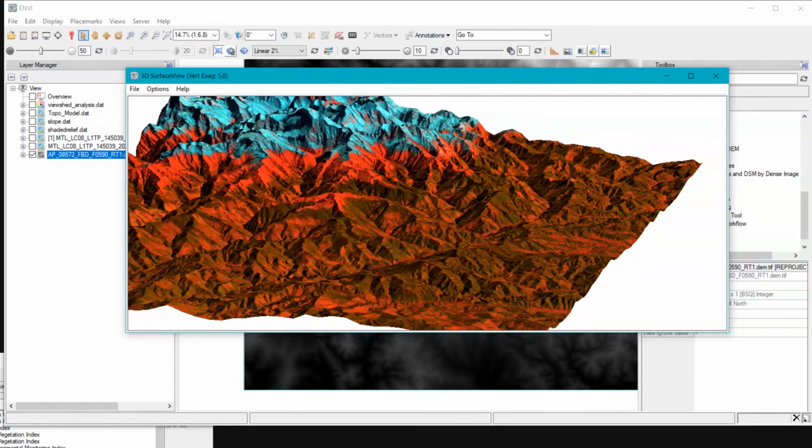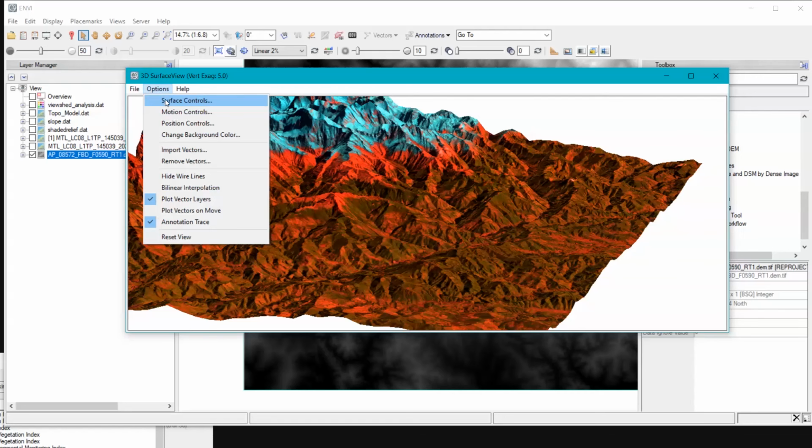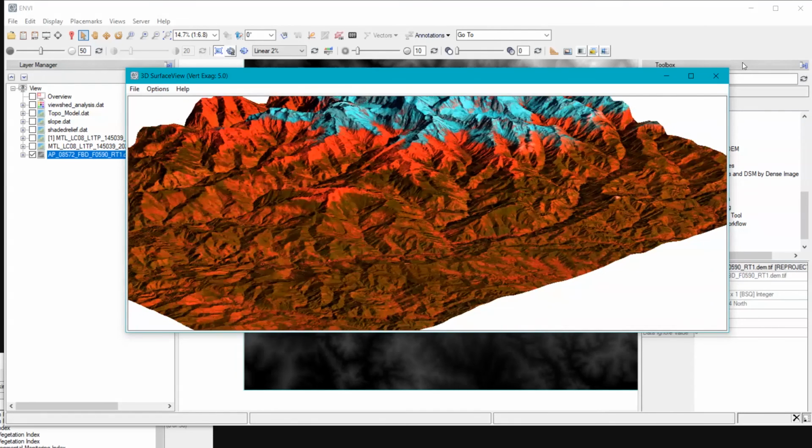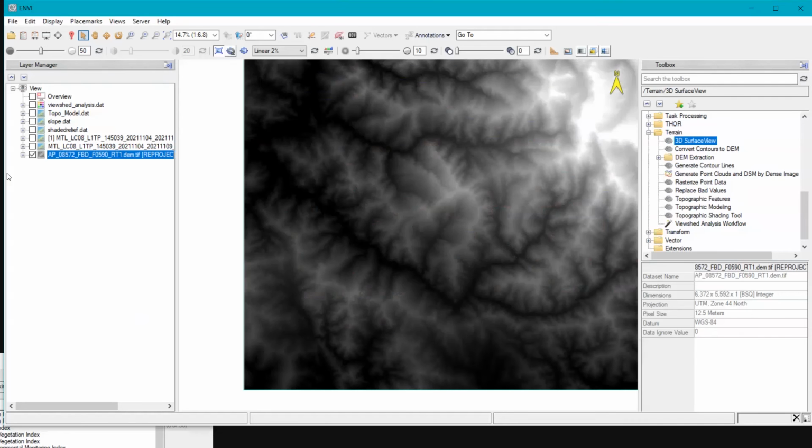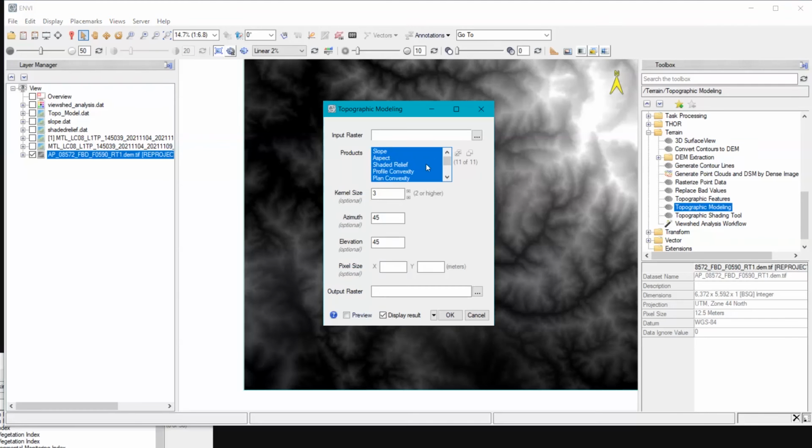A fly-through of a 3-dimensional data set is achieved using the saved views or a predefined flight path drawn interactively using the ENVI annotation tool. The vertical exaggeration, vertical and horizontal view angles, and altitude are controlled via user-selected parameters. The cursor is also linked to the draped 3D image, allowing extraction of profiles in X, Y, and spectral directions, as well as cursor locations and values utilizing the 3D projection.